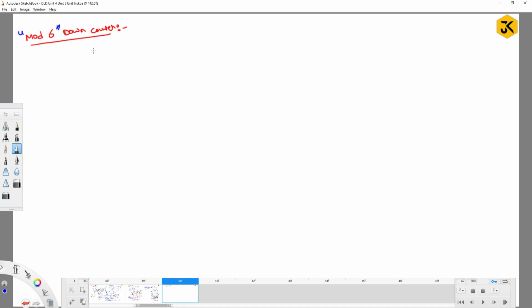If I have 2 bits, that is 2 flops, I can construct a mod 4 counter. If I have 3 flops, I can construct a mod 8 counter. But here it is not a power of 2, right? I hope you know the reason why I am saying powers of 2. So if you would like to construct the mod 6 down counter, you have to have some kind of logic changes. That logic you already understood if you watched the earlier video.